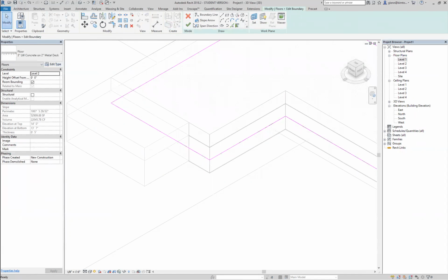So this whole issue of, for example, if I wanted to create an atrium, I could play around with all this work with the mass, or I could just do it on the pink line boundary of the floor. I know how to make an atrium. I could just go through and on this pink line boundary of the second floor, say, I just want to cut away that corner because it's going to be an atrium. And my pink line rules will apply. I need to trim it.